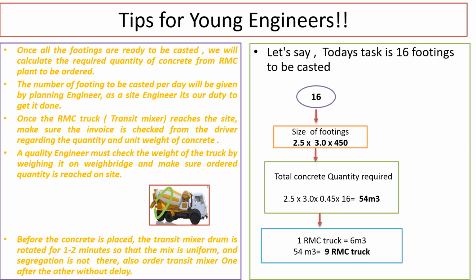Otherwise, if you delay it, like one vehicle comes and after 20 minutes the next vehicle comes in, then what is going to happen? The work which you had planned for 3 hours is going to take 4.5 or 5 hours. You're actually delaying your work, and that should not happen. So when you're placing the order, you should make sure the vehicle takes a minimum of 10 minutes to finish the work, and the next vehicle should be ready at your side so that there is no delay in the casting of the footing.